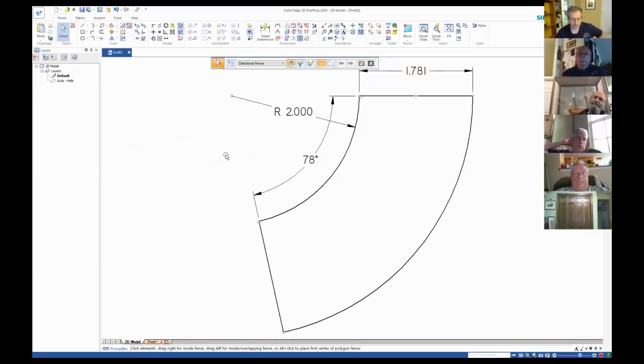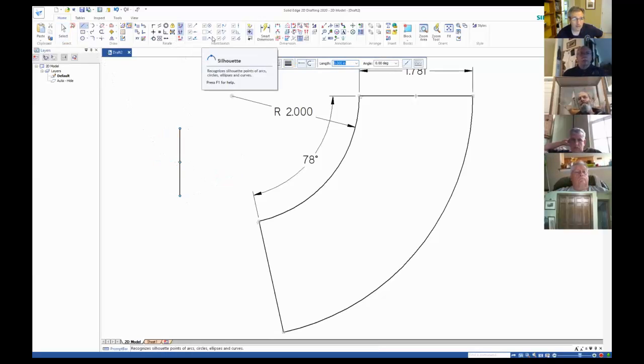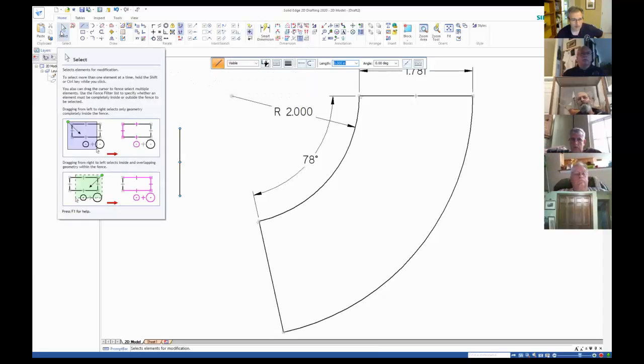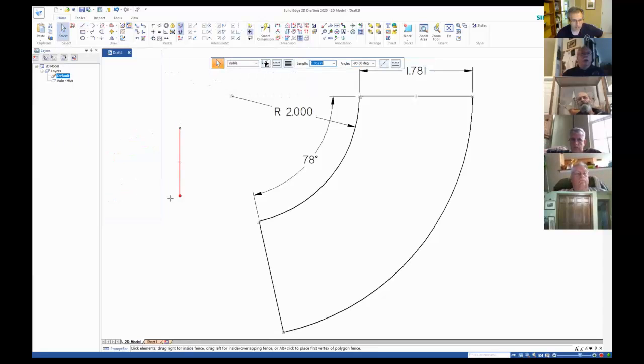I can do symmetry. So if I create a line, you can see that I have this, the horizontal or vertical. And if you draw one that's straight, it'll keep it straight. So if I try and move this now, it won't change the angle because this constraint is there. Oh, nice.